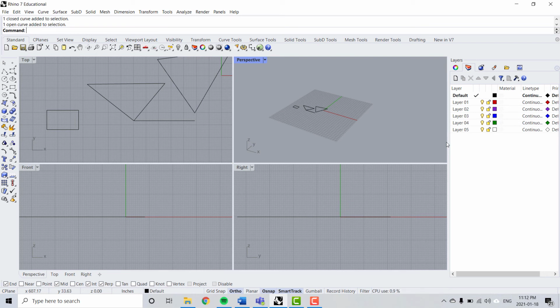So when it comes to floor plans, it's important to have various layers to introduce various line weights. So you want section cuts maybe to be on one layer, and then in a floor plan, in that case, it would be walls on one layer. Maybe you want furniture on its own layer because you want it to be super faint. Maybe you want doors and windows all in one layer. Begin to develop a structure of organization that relates to the line weights and how you're going to print this at the end.